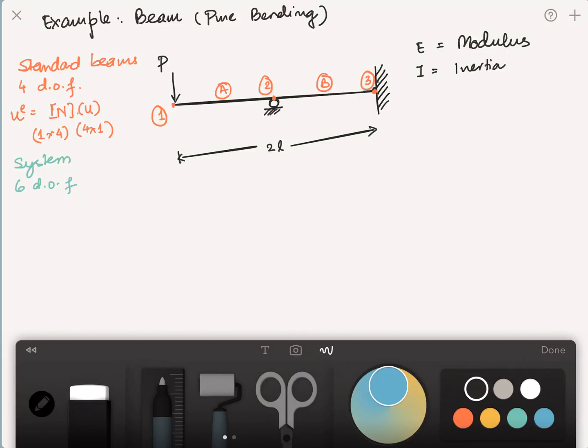Okay, so we can describe all the different degrees of freedom for each element, and therefore set up a displacement vector as well. We also know the boundary conditions of this system already, right? I'm going to make all the ones that are constrained in blue, because you see it. That means I am not allowed to move 2 in this direction. I am not allowed to move 3 in this direction or in this direction. That means I have 3 degrees of freedom that are fixed.